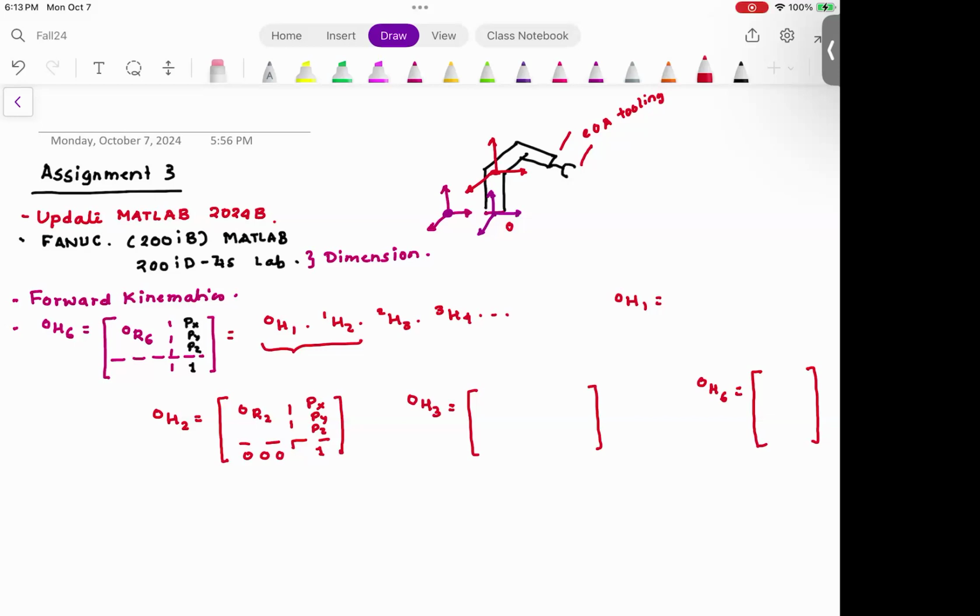Sometimes the robot manufacturer will give you their software. You program the robot in the software, and in software the robot is running fine. That does not mean you take that piece of code and deploy it on the robot. What you do is take a small piece of code, first move the first joint, then the second joint, third joint, and go through the entire cycle. Because otherwise you have this $100,000 robot hitting a $500,000 machine. And guess what? You'll be out of a job. So be extremely careful.